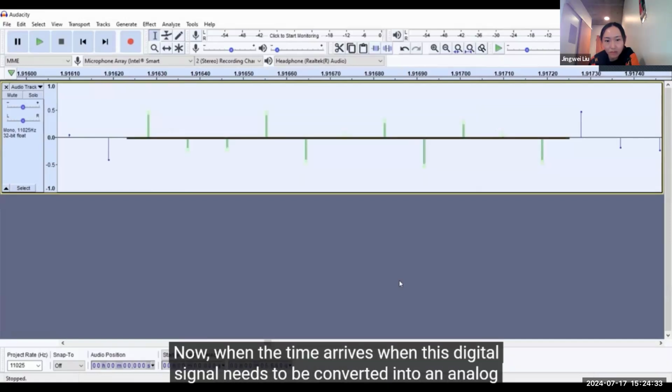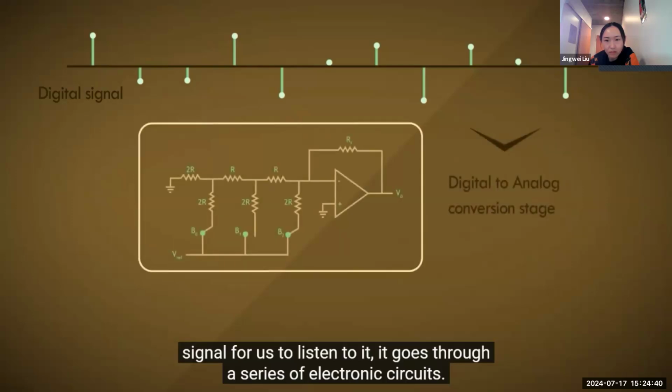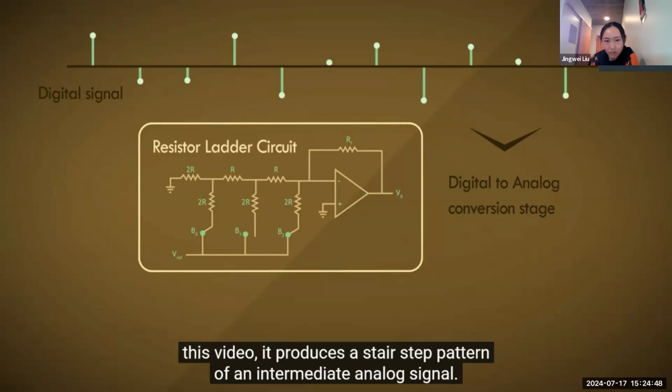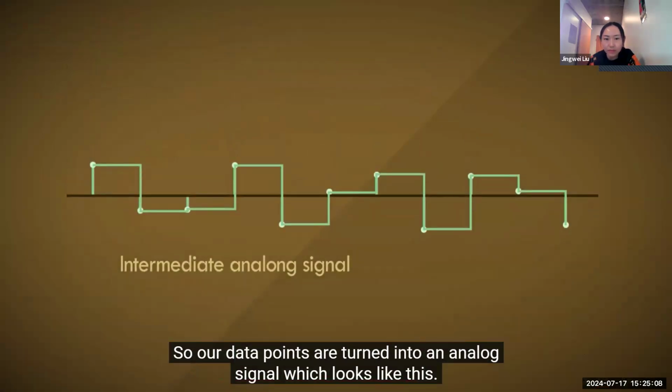Now, when the time arrives when this digital signal needs to be converted into an analog signal for us to listen to, it goes through a series of electronic circuits. In the simplest case, it goes through a resistor ladder circuit. And without unnecessarily complicating this video, it produces a stair-step pattern of an intermediate analog signal. So our data points are turned into an analog signal, which looks like this.